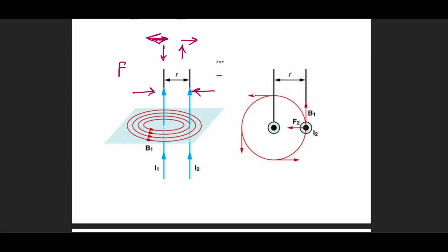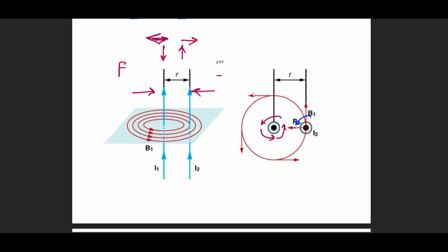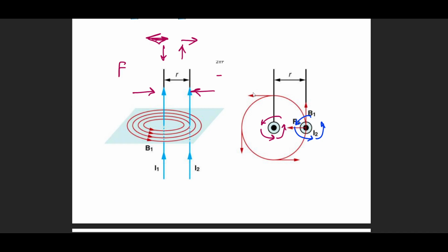And the reason for that is the strength of the magnetic field. Because of this dot model, let's say, the magnetic field is going to go like this. And the magnetic field due to the other current, which is in exactly the same direction with the dot model, is also going to have the same direction. So we see that at the very center, the magnetic fields are opposite to one another. The first conductor says magnetic field should go up. The second conductor says magnetic field should go down. So the magnetic field at the center becomes weak. On the outer side, if I choose conductor A for my direction of magnetic field, it matches with both conductors. So the outer magnetic field becomes stronger, and the magnetic force is from the strong region towards a weak region.